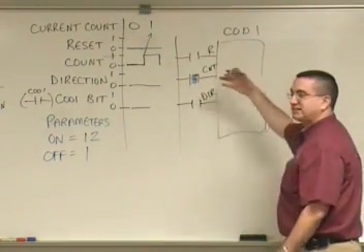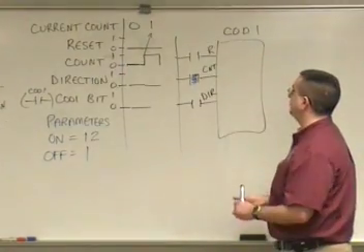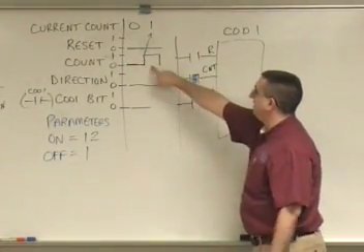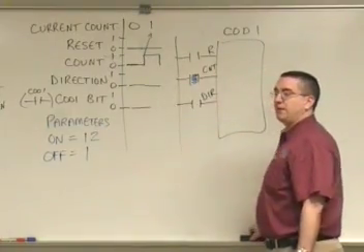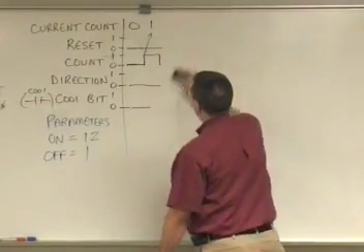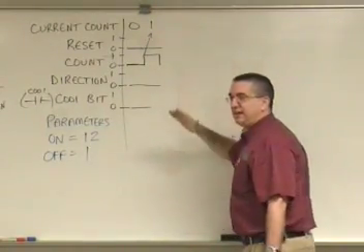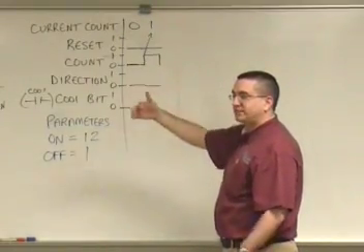So you're actually seeing what's happening here. That's what's going to be going on inside the PLC when I flip that switch on. I take that count pin high, that gives me a logical 1 on that count pin. Now if I were to just hold it high, it would just stay at a 1. It only does it on a 0 to 1 transition.